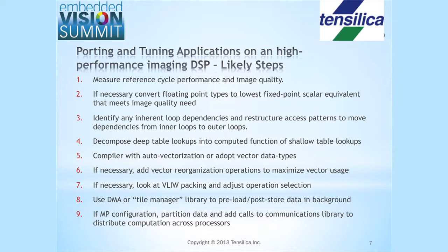Second, look at the data types. One of the big gains is going to come here if and when you can move away from floating point representation into a fixed point representation because of the throughput and energy ramifications of it. And in our experience, it's very often possible to do this. Sometimes you have to think a little bit cleverly about how you're going to retain the full precision of your fixed point data type as you move through.